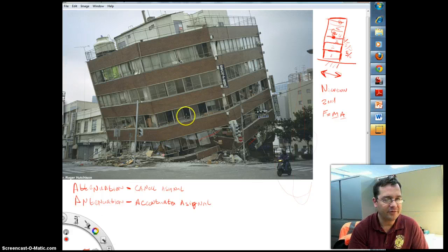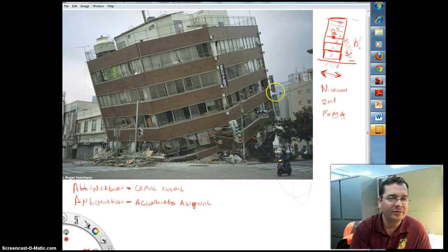So the story is that these first several stories of this building are somewhat flexible, and they play some role in attenuating the oscillations of the ground with the earthquake. So that helps. Now, why should these forces be proportional to the mass? Well, because Newton's second law says that the forces developed in the first floor will be proportional to the mass of the building. Why then the square of the height of the building? That maybe is not quite so intuitive.